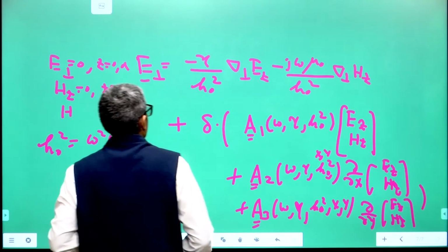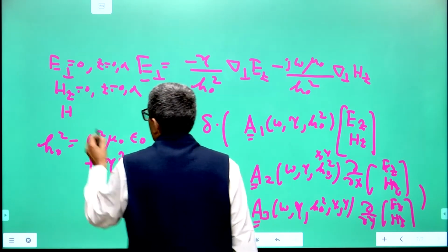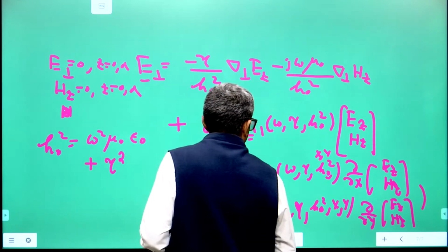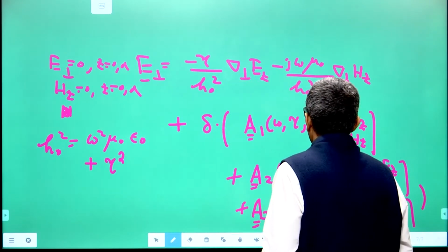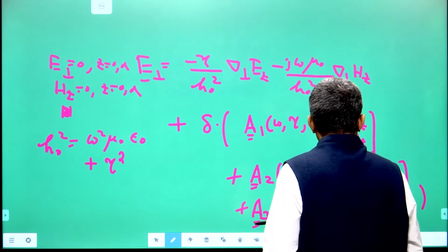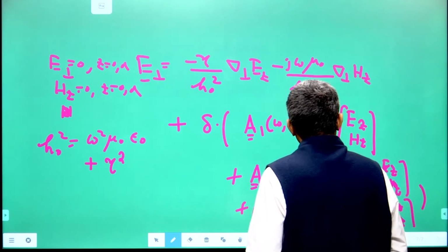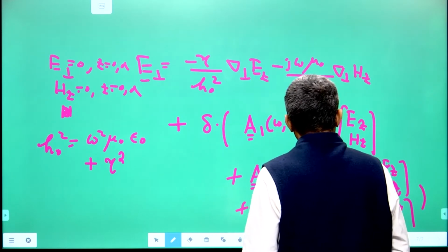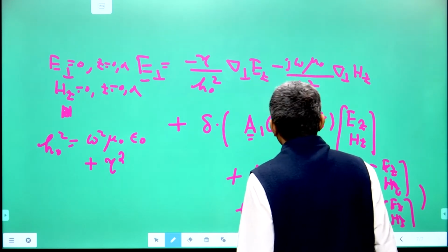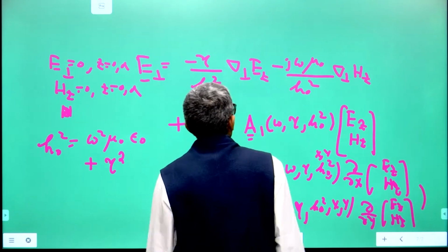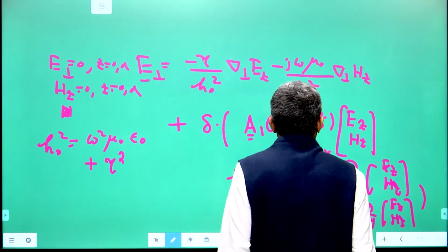And you have h normal, that means you will get an equation of the form for h perpendicular. So you will require that Ez vanishes, Hz vanishes, and you will also require the condition on dou Hz by dou n.